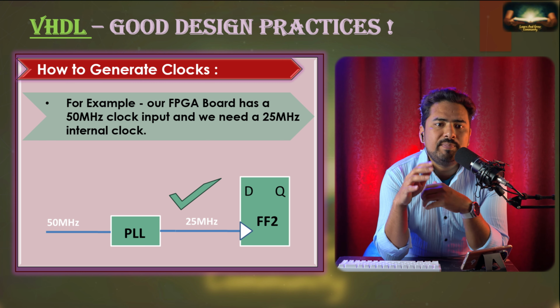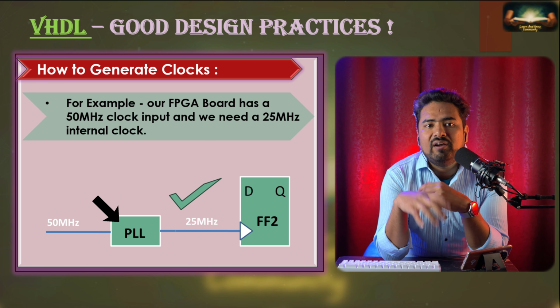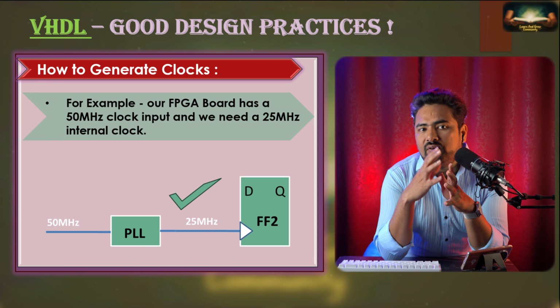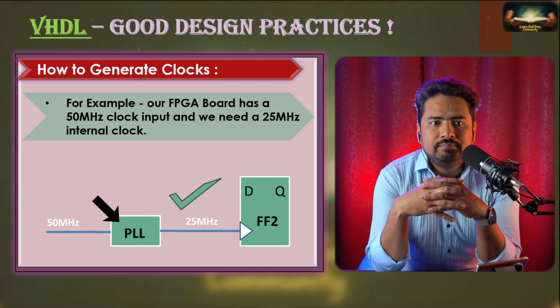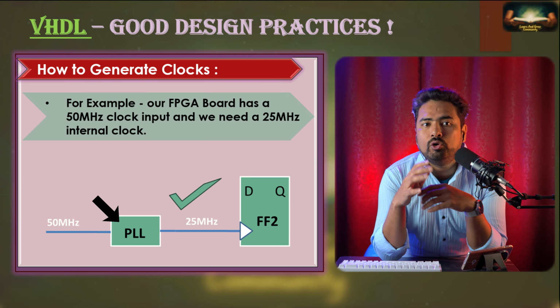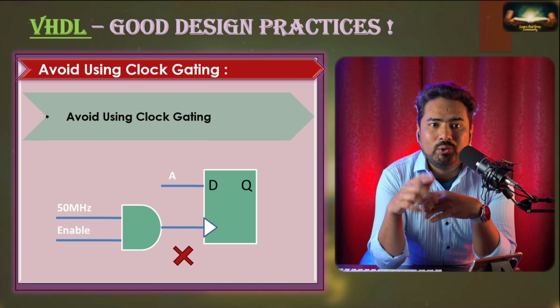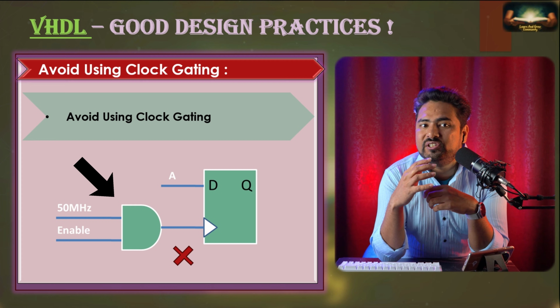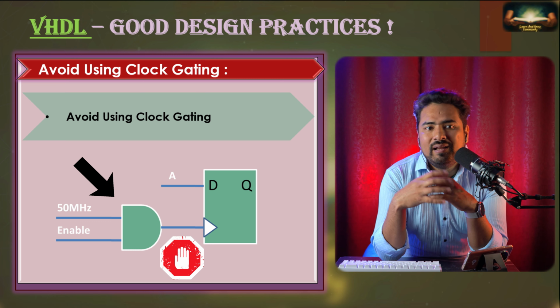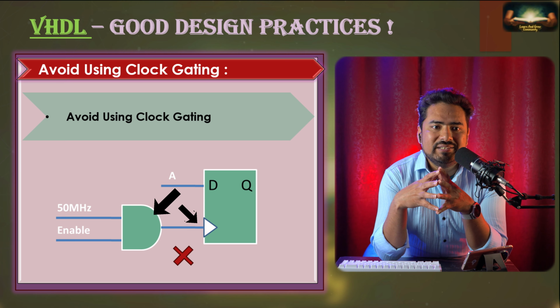Modern FPGAs typically have these built-in PLL resources and they are very easy to use to generate various clock frequencies. PLLs, or phase locked loops, can directly drive your global clocks in your FPGA designs. Also, this other approach is not a good practice either, when you add some gates or elements on your clock signals.